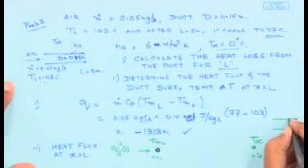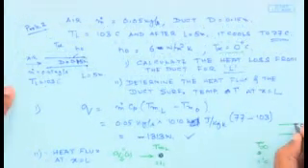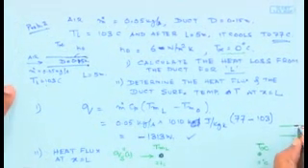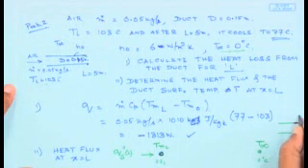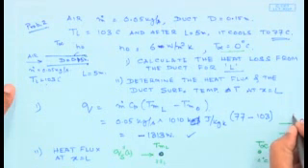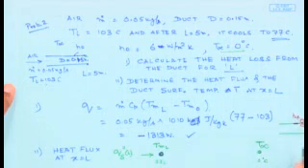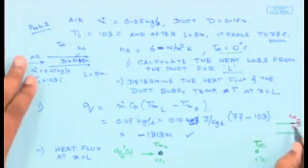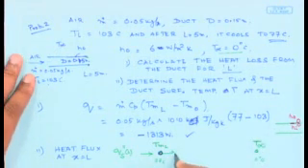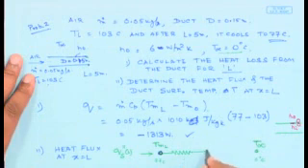The second resistance is in the tube itself, which we are neglecting since the tube thickness is very small, and the third is from the outside of the tube to the outside atmosphere. So this is the convective heat transfer coefficient on the outside, and this is the convective heat transfer coefficient at the inside, neglecting whatever conduction resistance we have in the duct. Therefore, if I draw a circuit, what I would get is something like this.